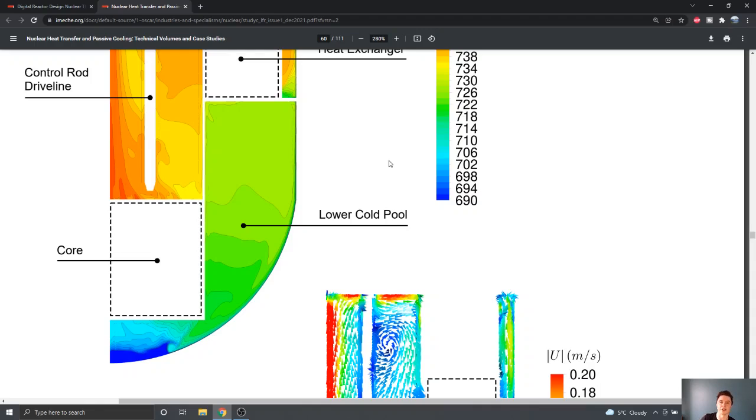And the reason for this, of course, is that our primary coolant is lead. We're not using pressurized water or pressurized CO2 or anything in this reactor. We're using liquid lead. Of course, liquid lead is a metal, so it's really conductive. And what that means is that the temperature variation throughout the reactor is actually quite small. The whole thing is almost at a constant temperature. There are only a few degrees of temperature difference throughout the pools.